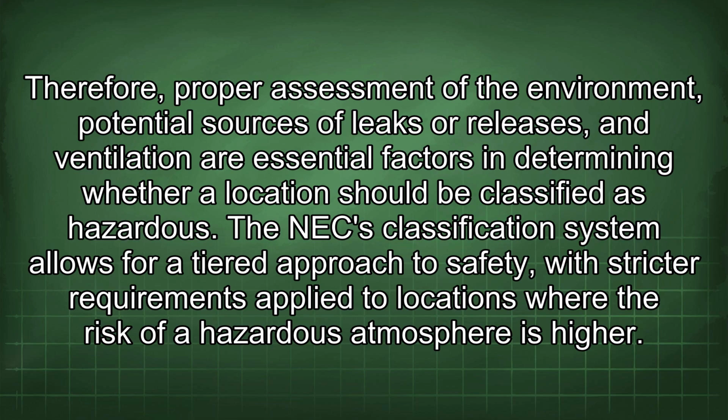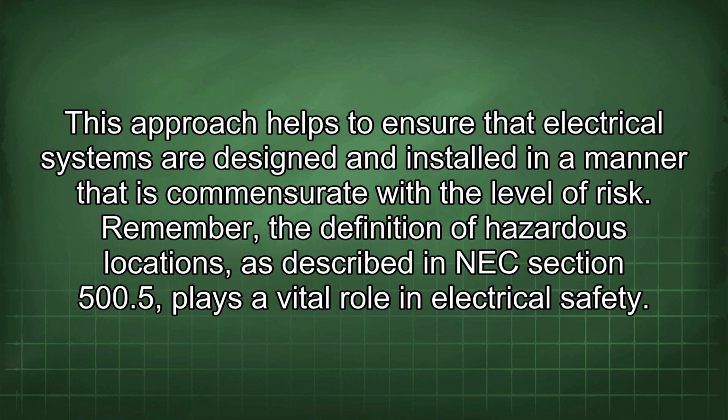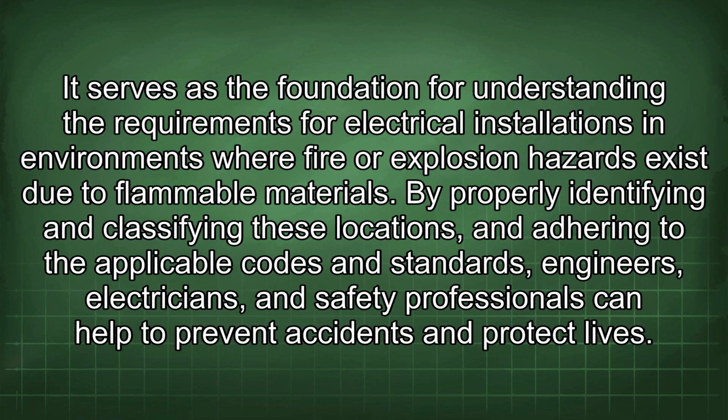The NEC classification system allows for a tiered approach to safety, with stricter requirements applied to locations where the risk of a hazardous atmosphere is higher. This approach helps to ensure that electrical systems are designed and installed in a manner that is commensurate with the level of risk. Remember, the definition of hazardous locations, as described in NEC Section 500.5, plays a vital role in electrical safety. It serves as the foundation for understanding the requirements for electrical installations in environments where fire or explosion hazards exist due to flammable materials.